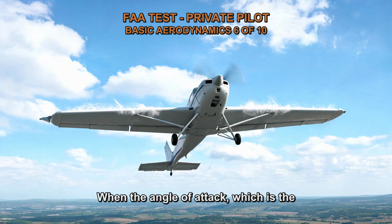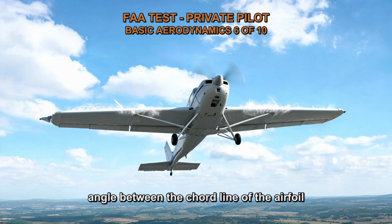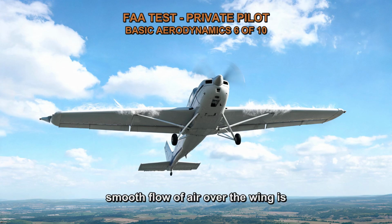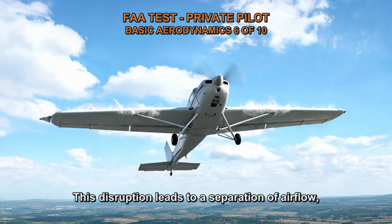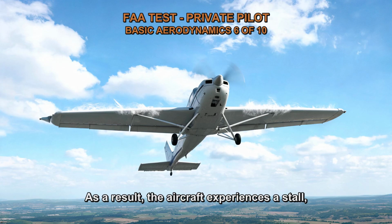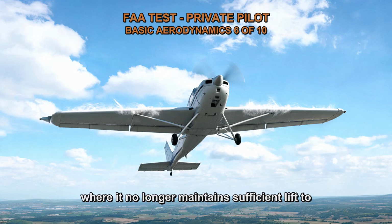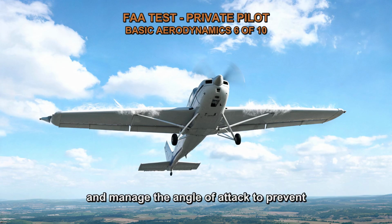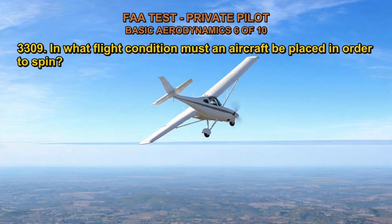When the angle of attack, which is the angle between the chord line of the airfoil and the relative wind, becomes too high, the smooth flow of air over the wing is disrupted. This disruption leads to a separation of airflow, resulting in a loss of lift and an increase in drag. As a result, the aircraft experiences a stall where it no longer maintains sufficient lift to counteract its weight. It's important for pilots to be aware of and manage the angle of attack to prevent stalling during flight.